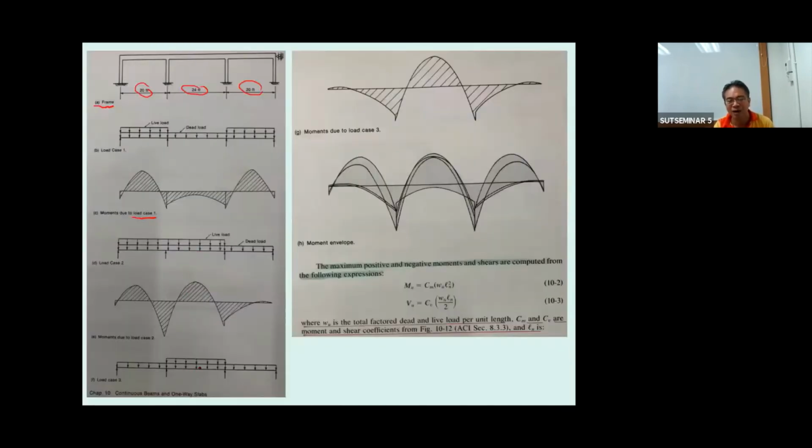And then this one is for the influence line diagram of the mid span of the beam. Okay, and then from this you will get the live load loading pattern like this. The load here is dead load. Okay, dead load always holds the span.